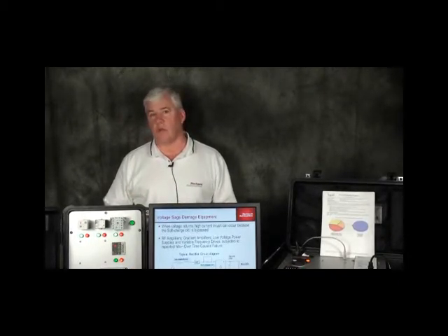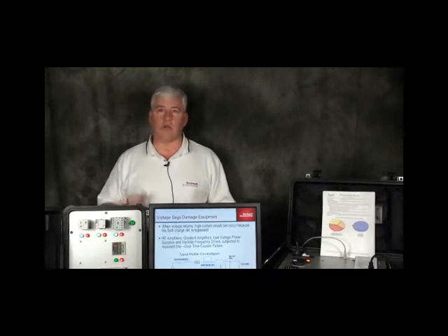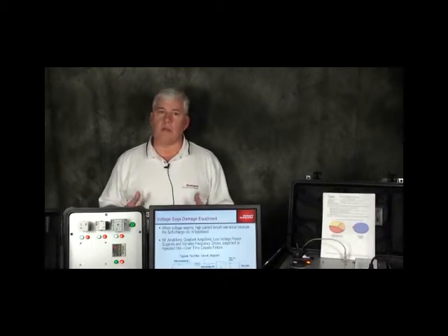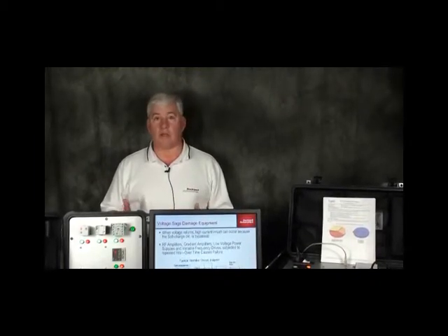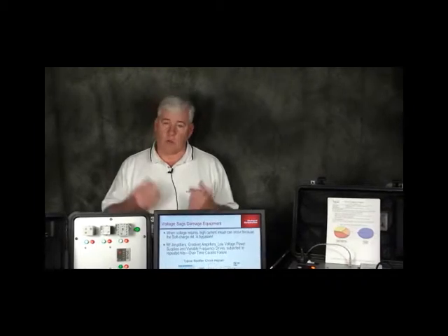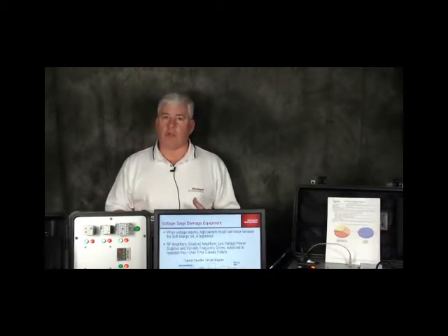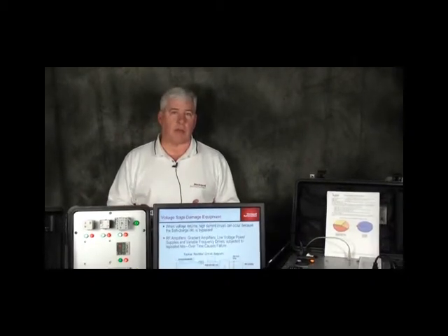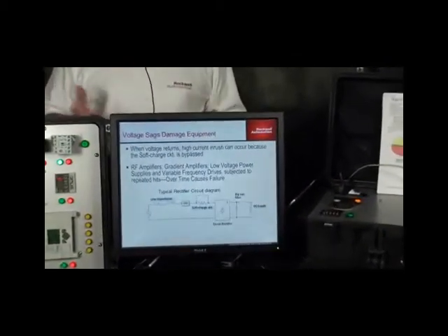I think this demonstration gives you a pretty good idea of what can happen to the manufacturing processes when voltage sags occur. Things will drop offline, sometimes mysteriously, and people are going to spend their time trying to fix problems that maybe aren't real, things that aren't broken, and so on. So what about when things really do break, right? Well, voltage sags have a very detrimental impact on power supplies. And of course, power supplies are just about in everything, including drives.